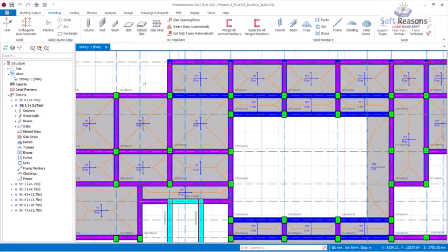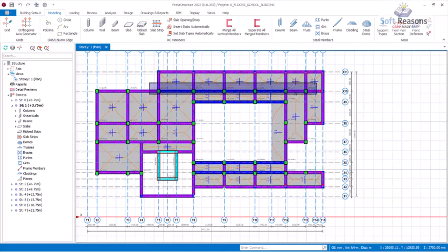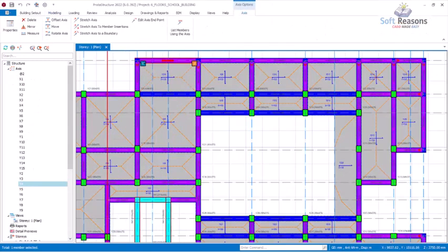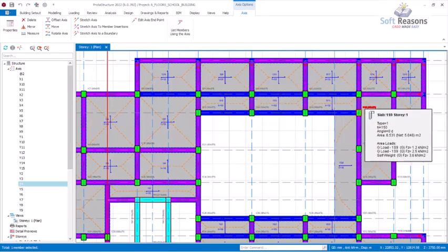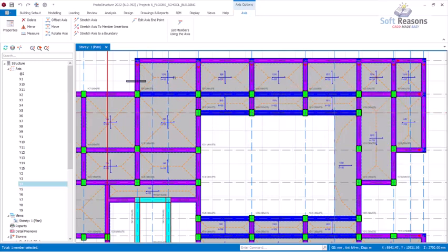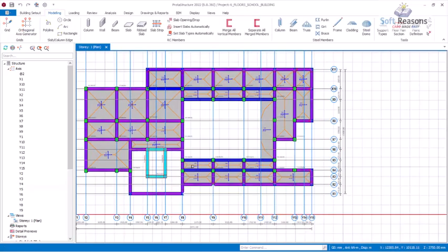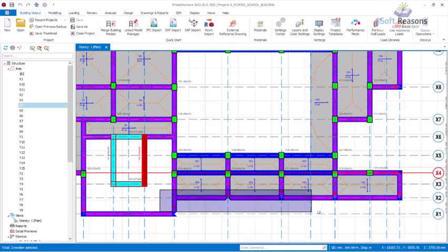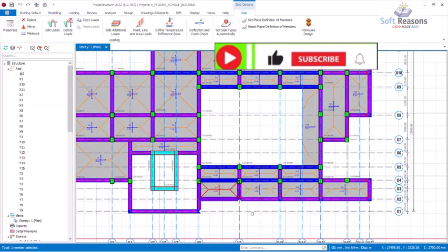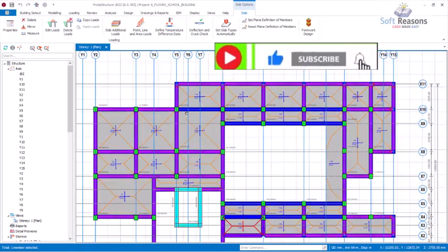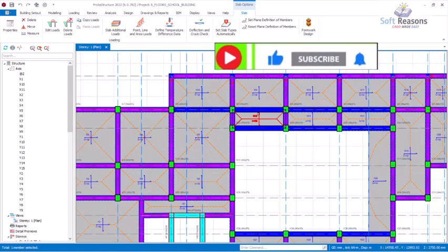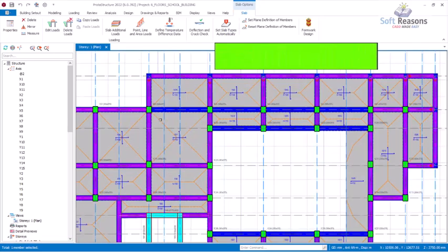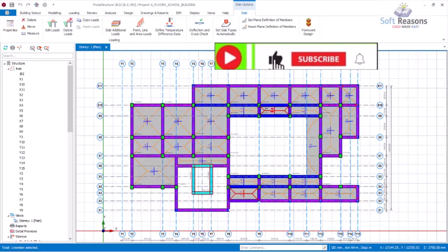The reason I said these columns are very important is that they are carrying cantilever slabs and beams. You can see the whole of this cantilever is being carried by these columns. The same thing applies to these reinforced concrete columns right here, which carry this cantilever. Pay close attention to those columns to see how you can interact with them to have economical reinforced concrete column sections, because this is the column that actually carries the whole floors.